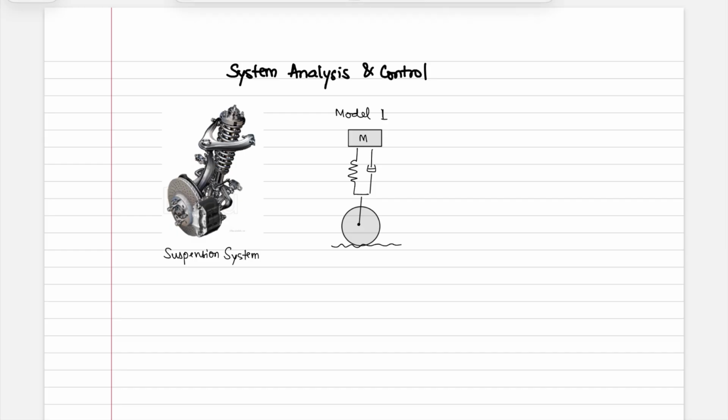But you could make the model a little more representative of the real world situation by having another representation where you have the same mass m, a spring, and a damper. And now you can have the mass of the wheel, or whatever it is that is going to move up and down. You have one mass here for that. That is actually called the unsprung mass. So the mass above over here is sprung by this system, while the mass here that is moving up and down with the road is the unsprung mass. Okay, this is just a discussion.